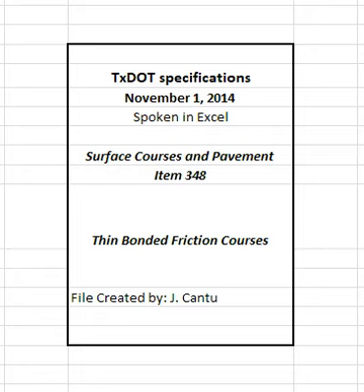4.6 Hauling operations. Clean all truck beds before use to ensure that mixture is not contaminated. Use a release agent shown on the department's MPL to coat the inside bed of the truck when necessary. Use equipment for hauling as defined in Section 348.4.7.3.2, Hauling equipment. Use other hauling equipment only when allowed.